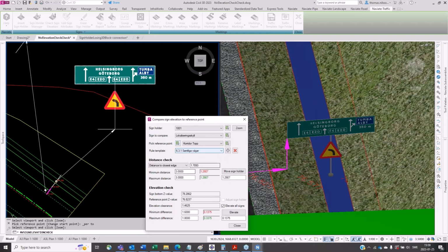Those rules are basically settings down here, and all you need to do is tweak these settings to another rule, click save here, and you can create a new setting for that one. I'll start backwards. I'll do the edit down here just to show, because this one says it's too low. The elevation clearance is 1.46. It needs to be at least 1.6.